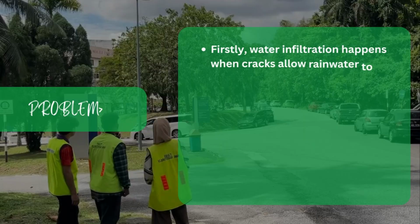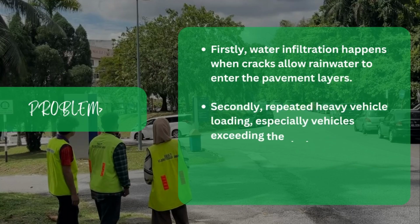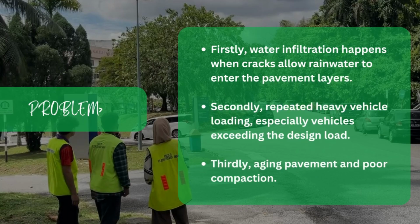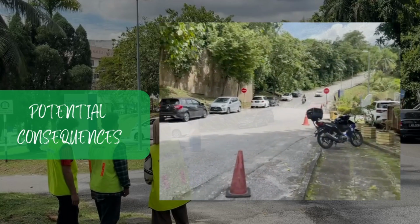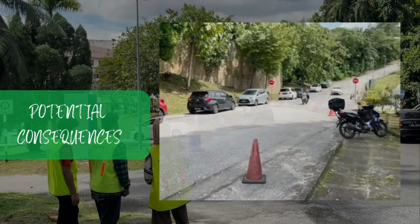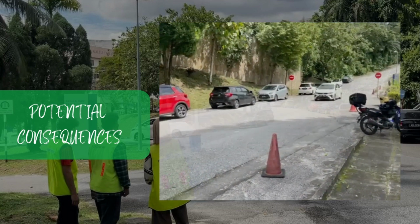Firstly, water infiltration happens when cracks allow rainwater to enter the pavement layers. Secondly, repeated heavy vehicle loading, especially vehicles exceeding the design load. Thirdly, aging pavement and poor compaction. These damaged road conditions can cause loss of vehicle control, sudden braking and swerving by drivers.